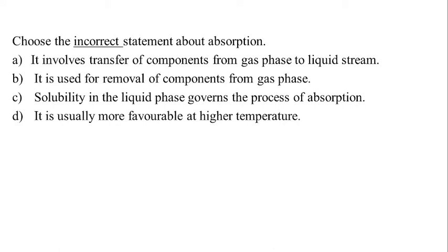In fact, the example which was given to you about H2S and CO2 removal from hydrocarbons by diethanolamine or monoethanolamine, there is a weak bond formed, and it's not exactly a physical process. There is a weak chemical bond which also forms, and that's the reason why you have a high solubility or high loading of the liquid phase.